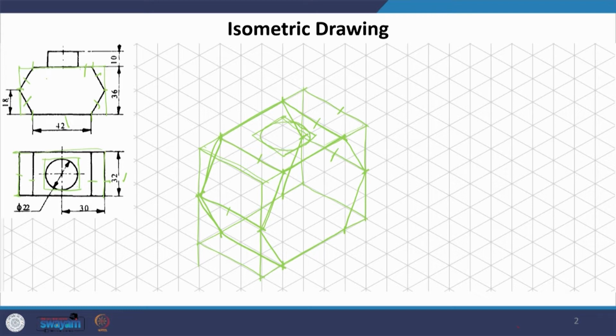Now, there is a certain height to it. So, we can also take the height, which is where the top circle is going to come. So, we draw another one at the top, or rather we could have drawn the top one first, and join the edges the way we join the edges of a cylinder, and that is it. So, we have the circle, which is what we are seeing here. We have these two edges, which is what we are seeing here, and the bottom of the circle and this. There is no other hidden line, there is no other line.